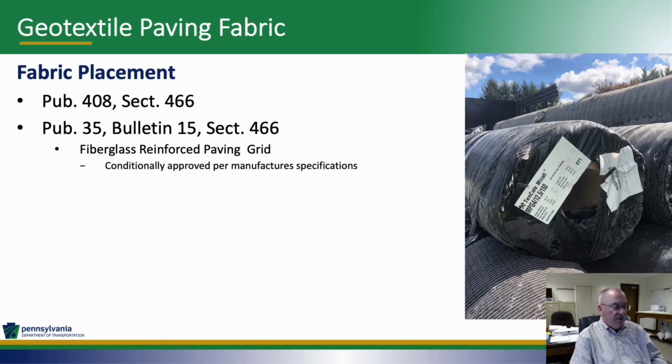The contractor applied the PG64 asphalt material using a calibrated distributor truck spray bar. The application rate must saturate the geotextile paving fabric to ensure bonding of the geotextile fabric to the existing pavement surface. We applied asphalt material at a rate of 0.25 gallons per square yard to completely cover the roadway with performance-grade asphalt binders.